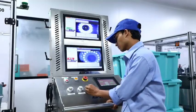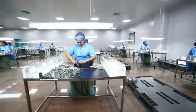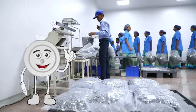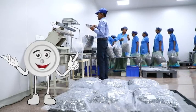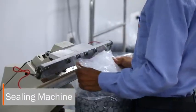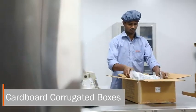After sorting by computer, visual inspection is also carried out by trained staff to detect any additional defects not otherwise detected. Rubber stoppers are packed in plastic bags of weight equal to the weight of 500 manually counted stoppers. The bags are then sealed using the sealing machine, which are then packed in cardboard corrugated boxes.